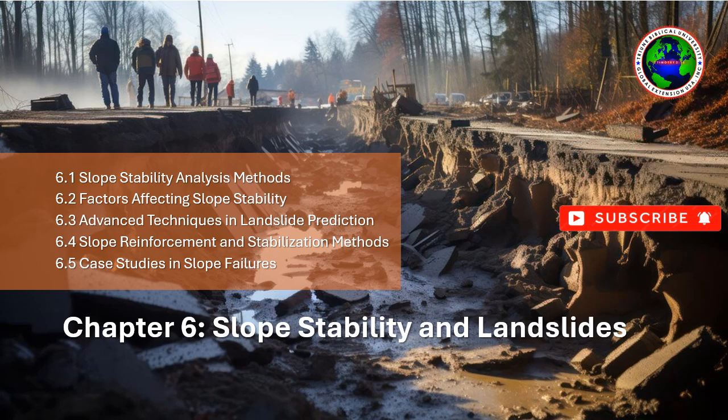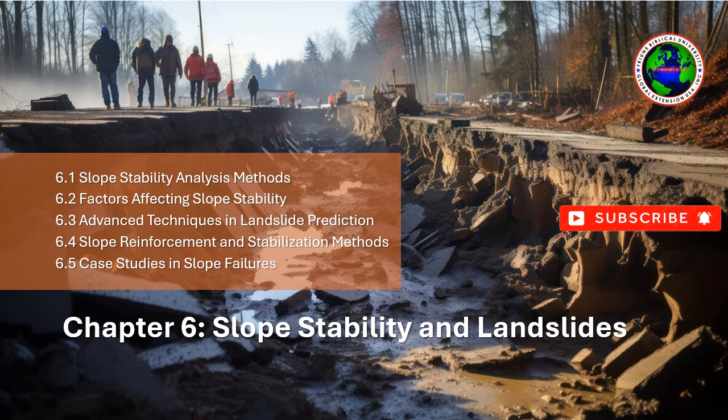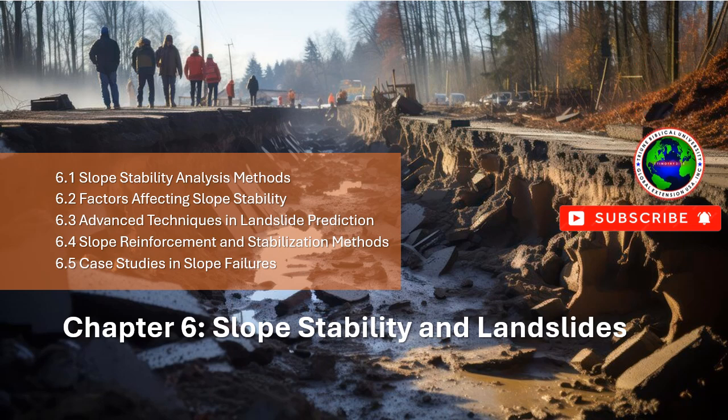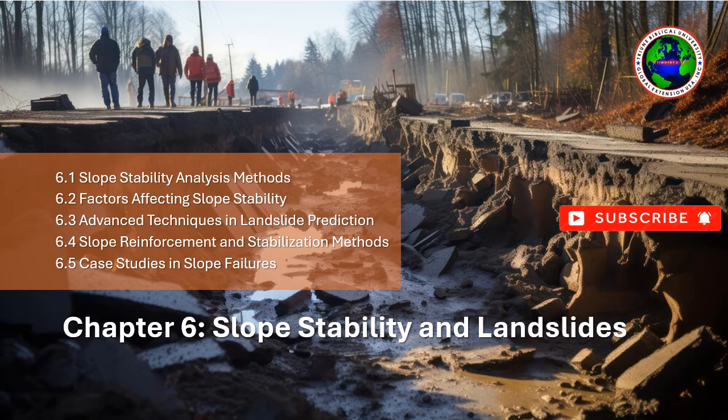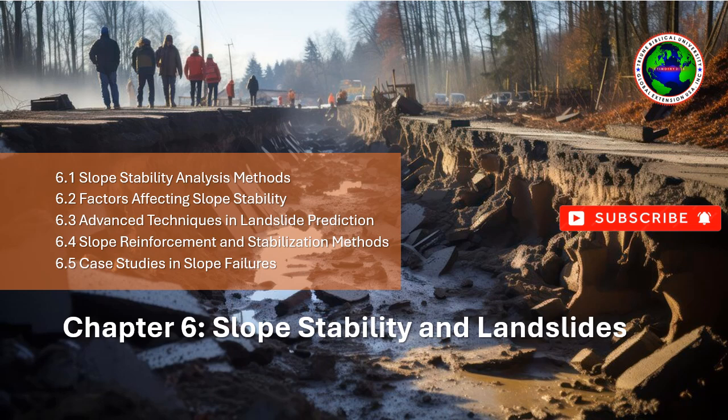Contributing factors: Geological instability. The area surrounding the dam had underlying geological weaknesses, including a fault zone and loose rock layers, which made the slope highly susceptible to failure. Heavy rainfall and reservoir-induced seismicity. Rainfall had saturated the rock formations, and the rising water levels in the dam reservoir exerted additional pressure on the already unstable slopes.